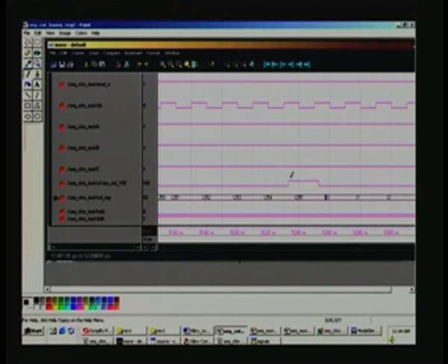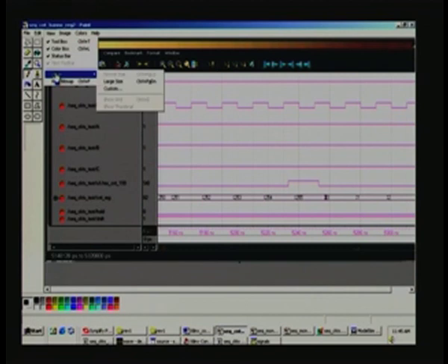So, probably we may have to write to ModelSim and find out why it is so, and that is not a serious thing, it is happening in advance here, both the edges you can see here. But anyway, after this pulse is encountered the counter has to clear, and that is what is happening here. You can even see some changes here before going to 0, it goes through some different values, but finally it settles down. So, if I zoom you may be in a position to see a little better.